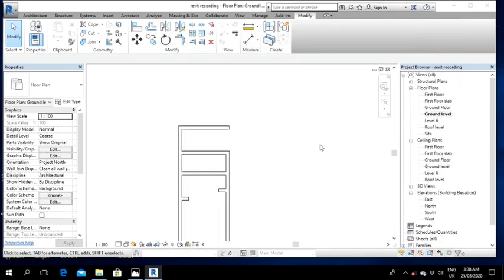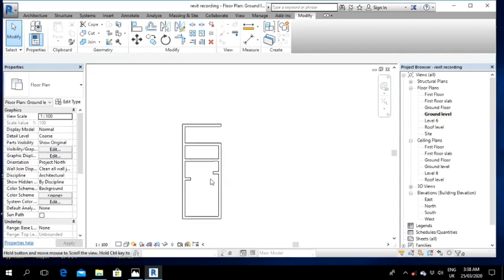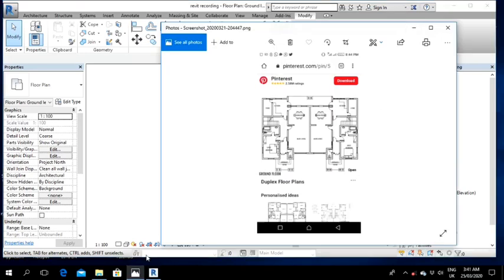So how we're going to do that: from here we offset this to come to somewhere here. Now to get the position of this particular wall here, we have to add this clear distance, which is 3 meters, plus the thickness of this wall, then plus this clear distance.